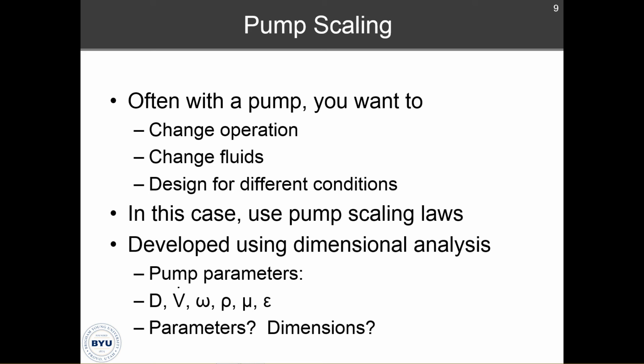In this case, we're going to use what we call the pump scaling laws. And these scaling laws were developed using the same dimensional analysis that we use to look at turbulent flow and laminar flow and a couple other things. So we're going to look at the pump parameters. This is going to look familiar to you since we actually did this on the test. You're going to look at the impeller diameter, the flow rate, the rotational velocity, the density, the viscosity, and the roughness.